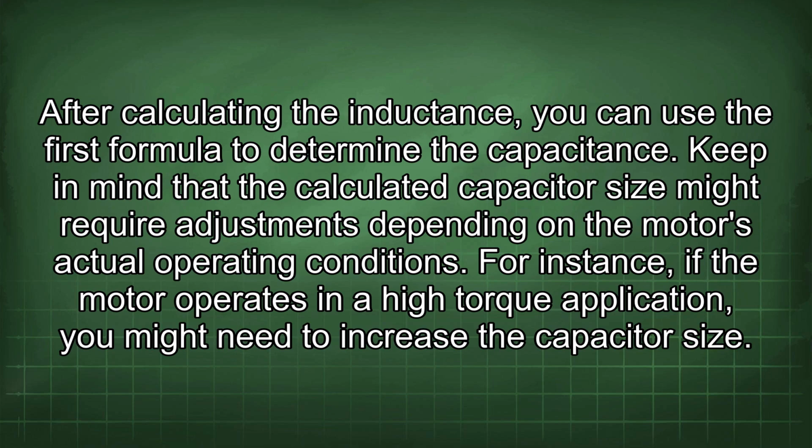Keep in mind that the calculated capacitor size might require adjustments depending on the motor's actual operating conditions. For instance, if the motor operates in a high torque application, you might need to increase the capacitor size.